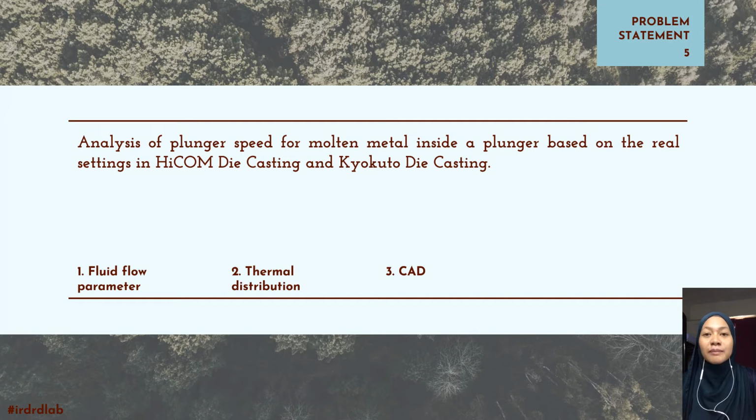The injection speed must be optimized, or else the turbulent liquid flow limits the air from escaping the mold and hence entrapment of gases occurs. Meanwhile, if the velocity of the molten metal in the plunger is too slow, it may cause backflow instead. Furthermore, highly imbalanced thermal distribution also causes porosity in the cast parts.